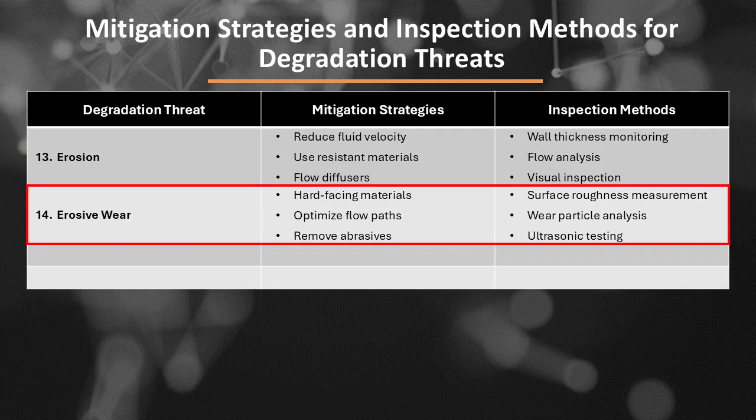Degradation threat number 14, erosive wear. Mitigation strategies for erosive wear may include hard-facing materials, optimize flow paths, and remove abrasives. Inspection methods for erosive wear may include surface roughness measurement, wear particle analysis, and ultrasonic testing.